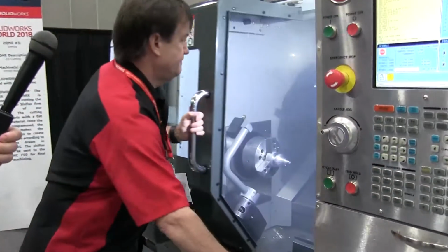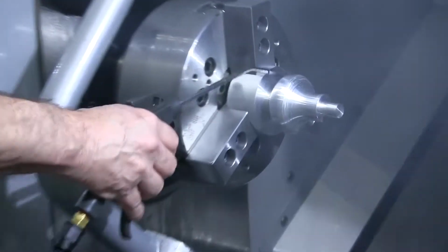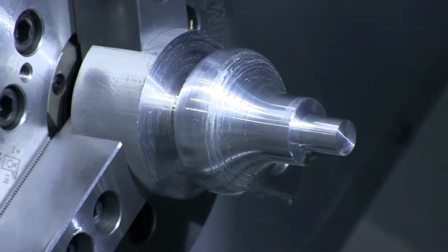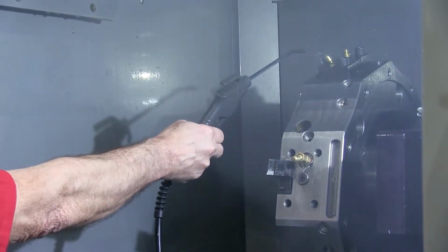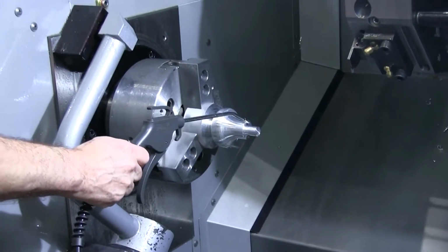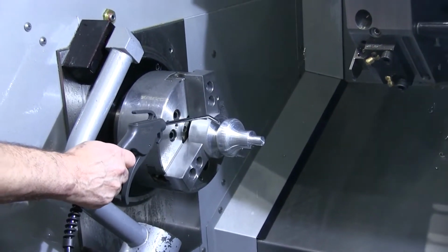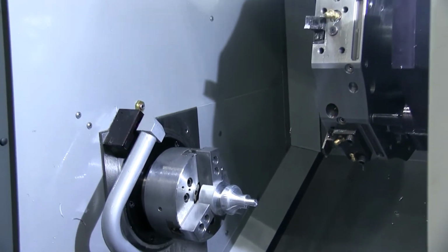This is important because this is ergonomic, and we want somebody to be able to grip this knob and have this entire profile finished with one tool. Wow. So that there's no step. Absolutely. Because you would detect that in your hand. Mm-hmm. So in order to do that, here's what we've done. We put this huge area of clearance behind here so that we can take this round insert and profile this entire profile in one cut with one tool.